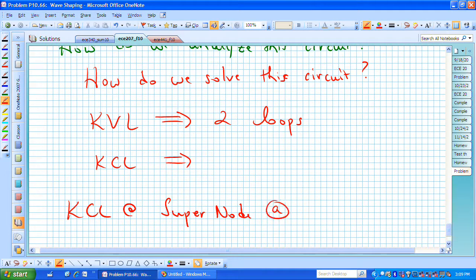A. If we go back, the KCL here, we had two node voltages. So that's seeming to indicate it may not matter if we don't simplify the circuit, whether we do KVL or KCL, and you guys would probably want to do KVL because KVL is more comfortable for you. That's fine, but let's just see if we can do this with KCL, and that involves then these two node voltages, V sub 1 and V sub 3.